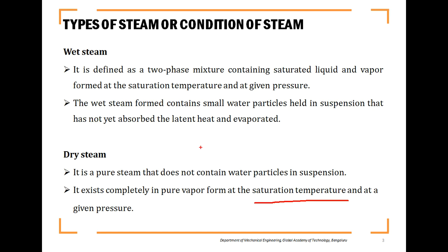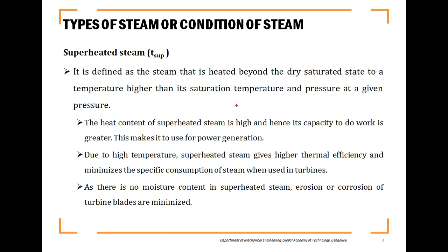Dry steam is nothing but pure steam which does not contain water particles in suspension. The third type of steam, what you can see, is superheated steam. It is represented by T suffix SUP. SUP stands for superheated temperature.